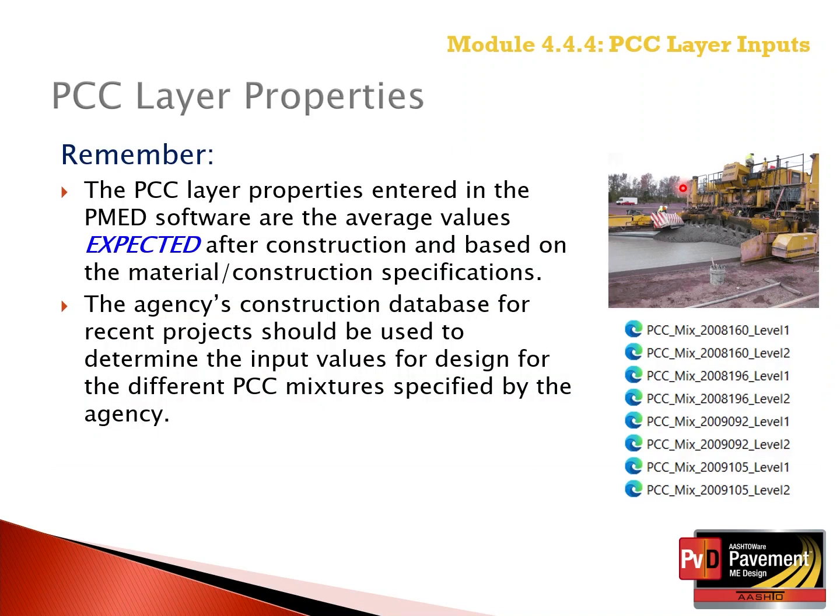Remember, the PCC layer properties entered in the PMED software represent average values for the specified PCC mixture that meet the construction specifications and were determined from historical or previous years' construction data of concrete mixtures that were found to be acceptable.